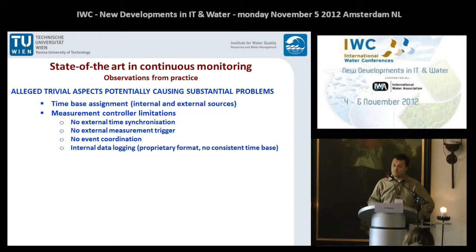You don't have any event coordination, often not even on the same instrument, so maybe you have one instrument that runs into a cleaning cycle with pressurized air, and then the controller holds that signal of that specific instrument. But if you have an instrument installed very nearby, you have the disturbance from the air bubbles, and not even the other instruments that are connected on the same controllers get a signal hold during this period. So you get some kind of artificial signals during these periods.